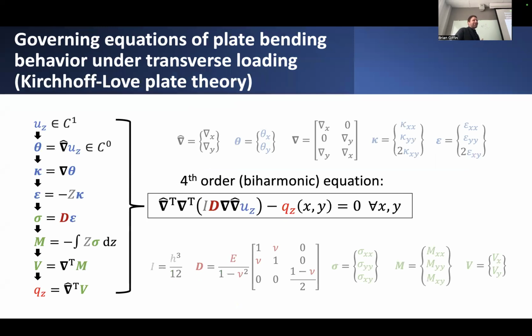The situation is actually quite similar, at least in concept, when we look at plates. Here, though, it becomes a little more challenging. Transverse deflection is, indeed, the single unknown field of interest that we're trying to solve for if we're looking at a plate subjected to some transverse loading Q that acts in maybe the Z direction. Let's call that the transverse direction. So we want to know the resulting transverse deflection under some applied transverse loading. We can relate all these different quantities in a similar fashion to one another. We can push them all into one big equation, and we can solve for this resulting transverse deflection.